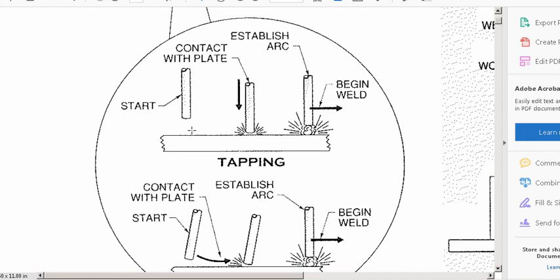But essentially that's what you've got. At this point in the process, both electrodes are ready to go. There's plenty of electrons ready to flow right now in here, and they want to get to here. It's charged and ready. It's not until the point of contact is actually made that you get that flow going, get that arc created, and have that essentially continuous arc occurring as it moves along. So here the electrons are flowing freely. In both these two cases here, they're just potentially ready to go once the tap occurs. All right, so there's your basic visual version of the principle. Let's look at the terminology and things that are actually occurring in these processes.